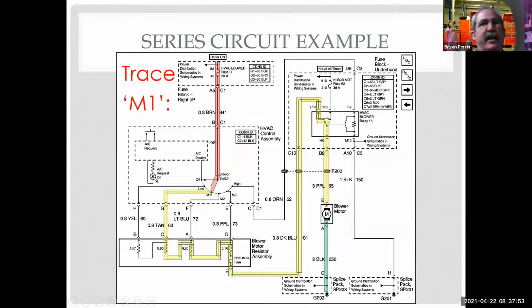And how much that is depends on what my applied voltage is. I have the value of the resistors. We could do some math, make our heads hurt, and I could confuse you further, but that's not the point. The point is that I'm going to have system voltage here, less here, and even less here, because as I go through the resistors, I'm using up some voltage. And really for testing, that's all I need to know.